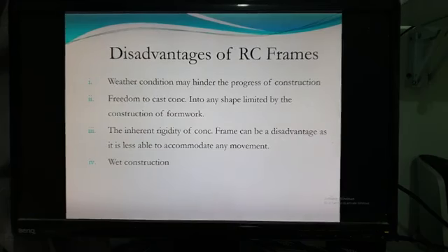So that's why for very tall RC buildings which are being built in earthquake-prone areas, they would put like bearing pads under the superstructure to give the RC superstructure a little bit of flexibility in terms of horizontal movement when there are any earthquake happening.